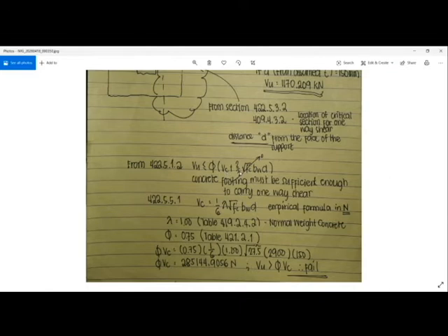So yung Vs natin is your shear reinforcement, no? So we all know na hindi natin pwedeng lagyan ng stirrups ang footing, so therefore your concrete should be strong enough to carry one-way shear.